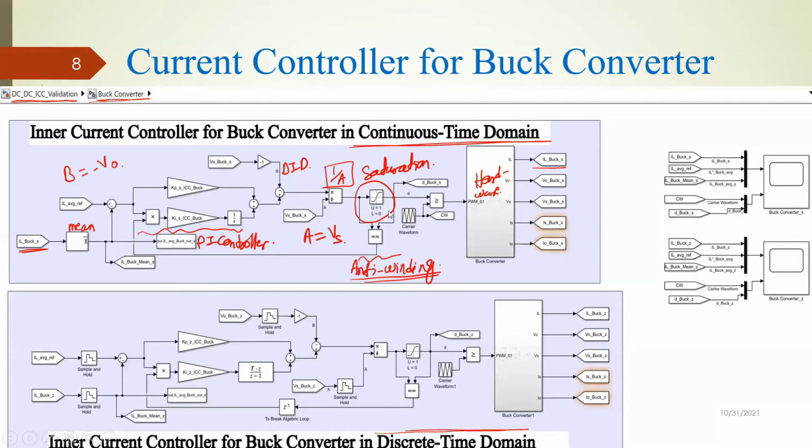So you should be very careful implementing this, and you would see the importance of this anti-windup especially in the output voltage control loop, when you want to operate in a safe region using the saturation of average inductor current. There you can actually see the difference in the implementation when you have anti-windup or you do not have anti-windup. Okay, so this is important, you should have it. So this is how the control was structured.